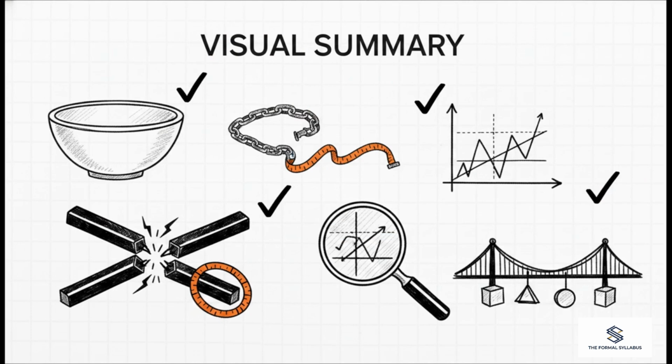So, to wrap up today's lab assignment, here are your actionable recommendations. First, when modeling complex physics in software, always prioritize convex mathematical formulations. Second, parameterize along the object's length rather than an arbitrary axis to massively increase computational efficiency. Third, use constraint relaxation, turning hard equalities into inequalities to completely bypass non-convex numerical failures. Fourth, always check your dual and primal values to interpret the accuracy of your convergence. Basically, if your dual infeasibility doesn't approach zero, your model needs adjusting. And finally, remember that a robust model easily allows you to adjust mass distributions to adapt to real-world loads.